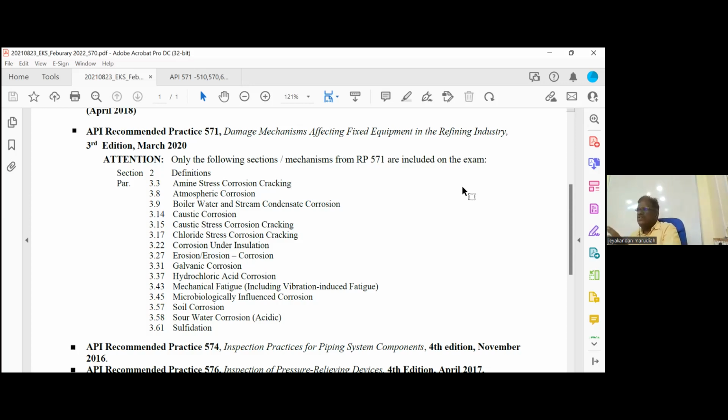So if you have a doubt that the pipe became brittle during service, they will keep the acoustic emission probes and start pressurizing. When any crack starts, they will immediately stop the hydro test. So if the pipe becomes brittle, we have to remove the brittleness. Brittleness can be removed by heat treatment. So that is acoustic emission testing.